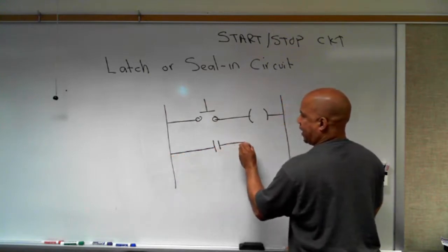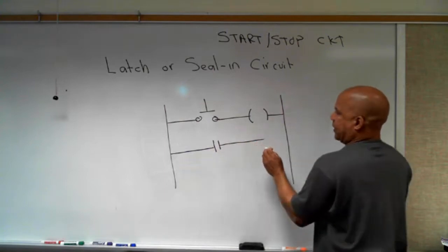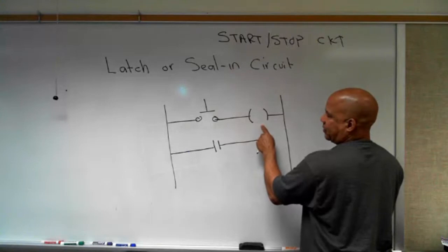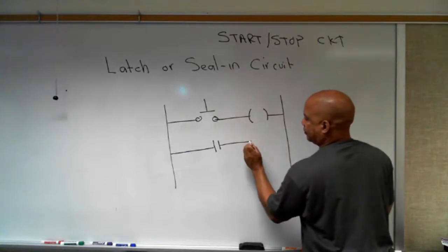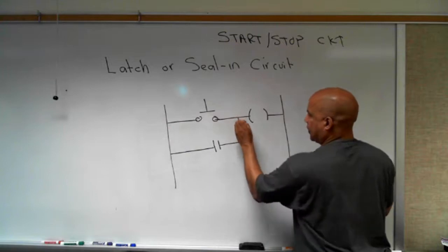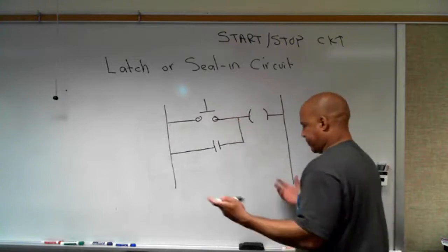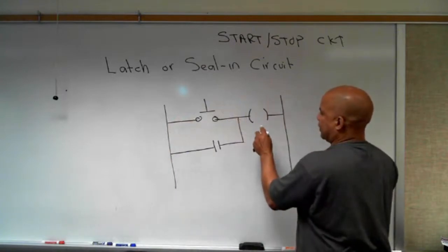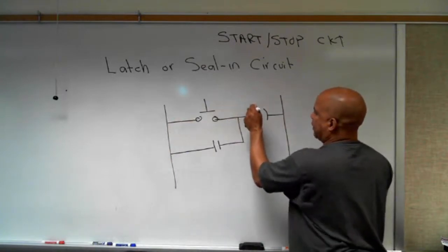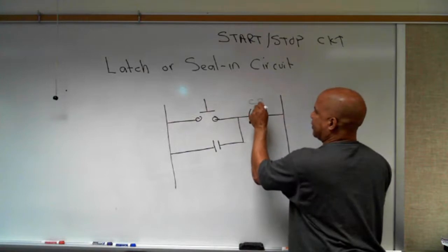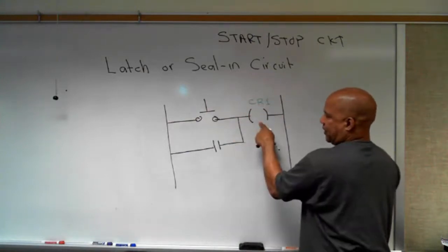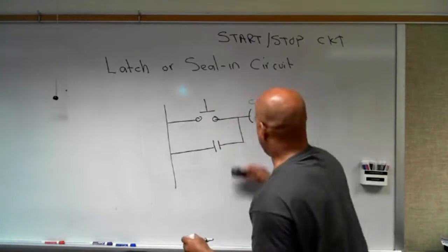But what you're going to do is you're going to have another contact right here. And that contact, you give it the address of this. So let's say the address, I don't know, I'm just going to call it CR. So here's the address of this. So I have this push button, I have this relay. So you can see how that works.